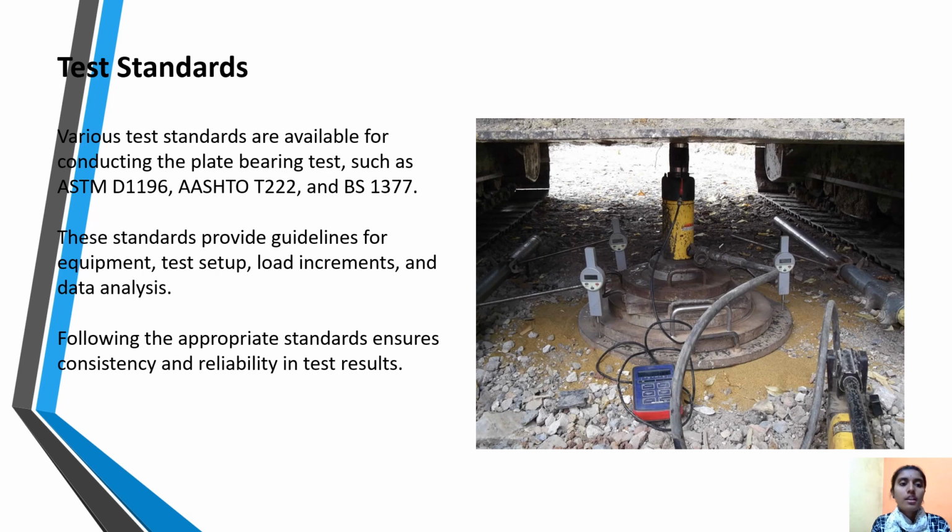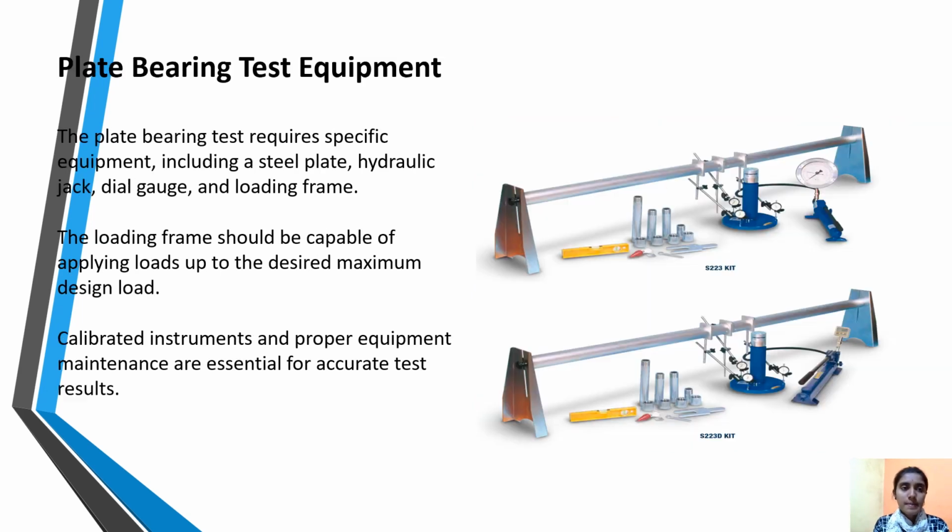Test standards. Various test standards are available for conducting the plate bearing tests such as ASTM D1196, AASHTO T222 and BS 1377. These standards provide guidelines for equipment, test setup, load increments, and data analysis. Following the appropriate standards ensures consistency and reliability in test results.